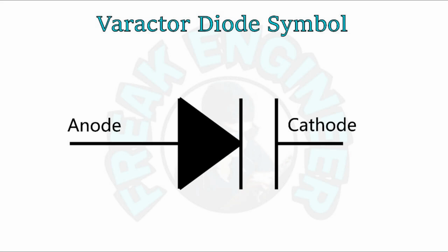Frequency modulation, FM: voltage-controlled capacitance is used in FM modulation circuits, where the capacitance is modulated by an input voltage, causing the output frequency to change accordingly. Voltage-controlled capacitance is a powerful tool in RF and microwave circuit design, enabling dynamic control over circuit parameters for applications like frequency tuning, modulation, and voltage variable filtering. It plays a critical role in modern communication systems, allowing engineers to achieve precise and flexible control over the behavior of electronic devices.